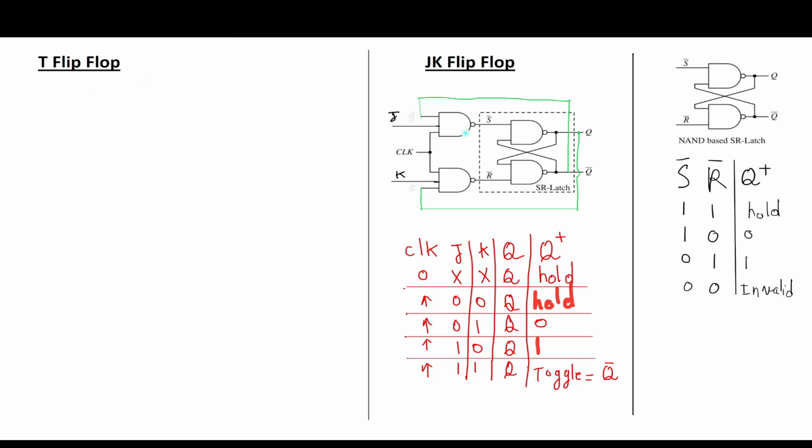So in the previous video, we learned how we can design the circuit for JK flip-flop from an SR flip-flop circuit. We saw that we can feed the Q state back into this NAND gate, make it 3 inputs, and we can also feed the Q bar back into the upper NAND gate and make it 3 inputs. So let's take a copy of this JK flip-flop circuit and modify it to make it a T flip-flop.